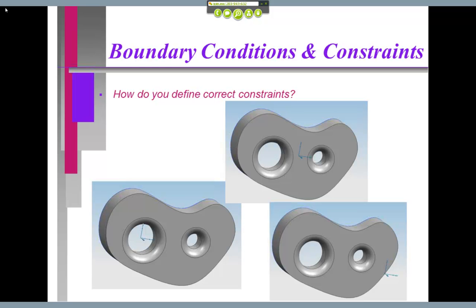Nothing. It's going to say, you told me not to move and you put a force on me. I can solve that and not move. So you're going to want to hold it some other place, and maybe the place that you hold it is in the middle of this thing, and you say, I'm loading the heck out of the front right upright, okay? Now, is that reasonable, to hold it in the middle?